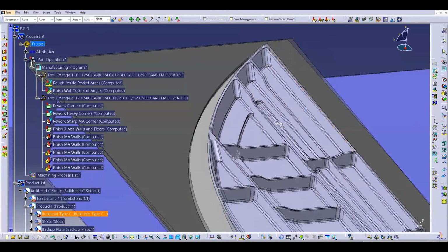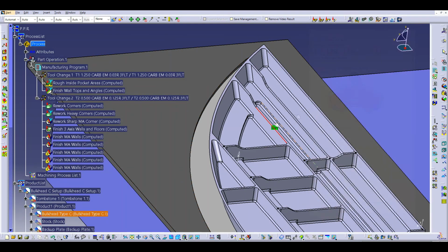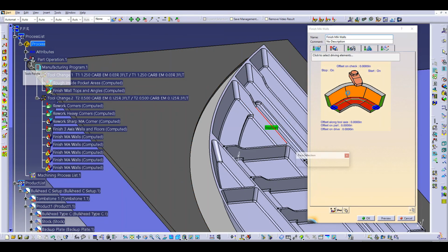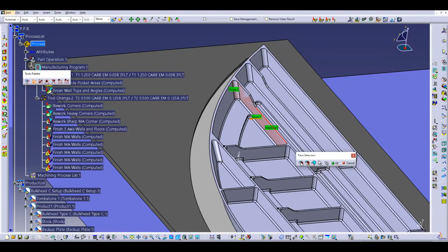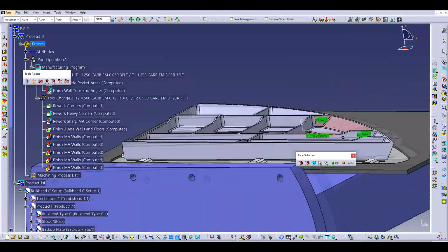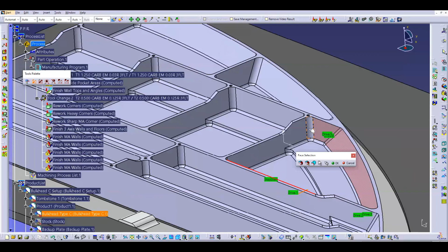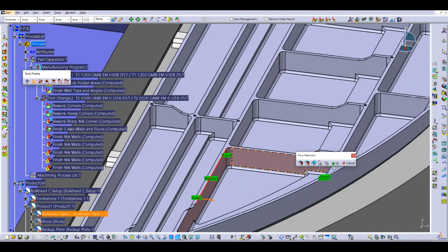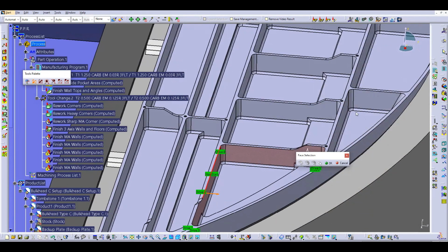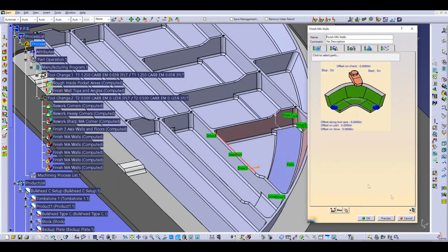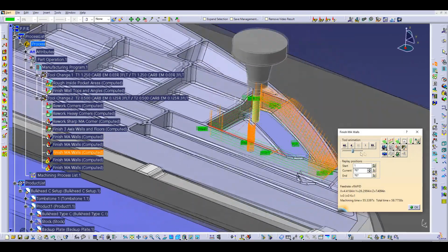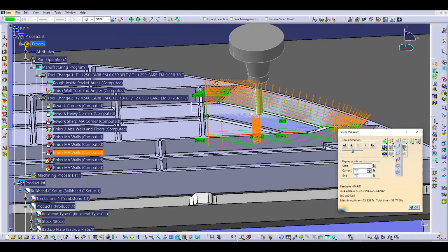Same type, we're going to come over and select our starting and stop points. And now on this one, I'll use full navigate. So it navigates around until it can't find its way for whatever reason. And then I can select the other pockets, or excuse me, the other surfaces. And we'll select our bottom, compute that. So I'm going to go ahead and turn my vectors off at this point. Turn it back to non-vector display.